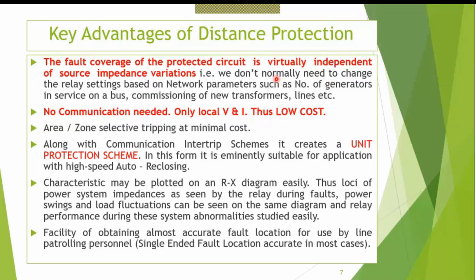In overcurrent, what happens? When the fault level behind the relay location increases, the time of operation decreases. So we have a little bit of difficulty. Network parameter change affects overcurrent and earth fault very much. But distance protection is not affected by source impedance variation, meaning fault level variation.